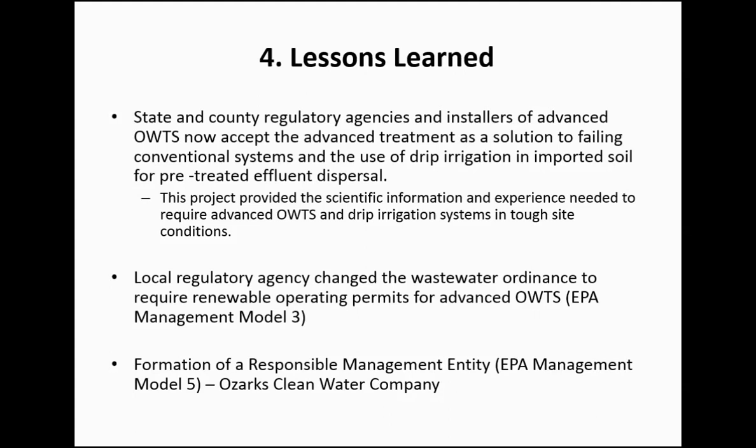This project provided the scientific information and experience needed to require advanced on-site wastewater treatment systems and drip irrigation in tough site conditions. The local regulatory agency changed the wastewater ordinance to require renewable operating permits for advanced on-site wastewater treatment systems, which is EPA management Model 3.